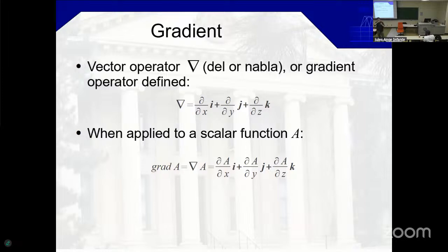It looks at the difference in pressure in all directions, and it will have 3 different components that resolve into a single vector. The pressure field is nothing but a field of scalars. You can measure the pressure at any point. It doesn't have a direction, the pressure itself. But the resulting gradient is a vector field.